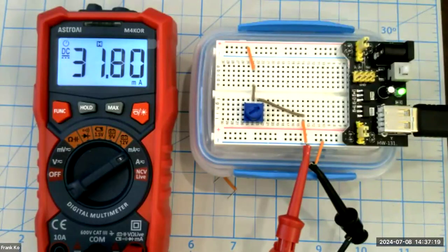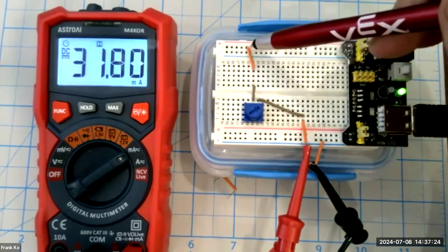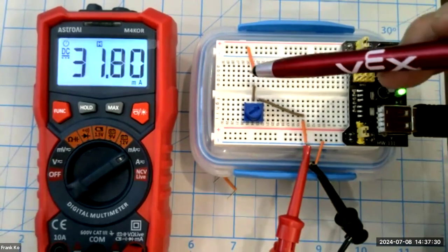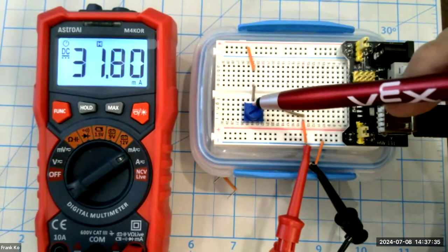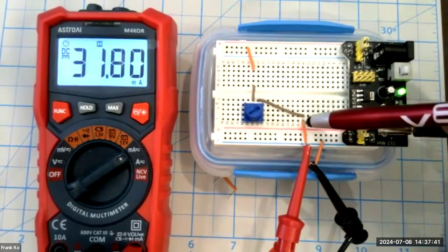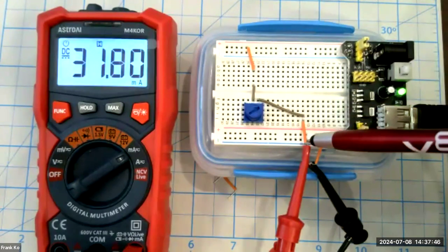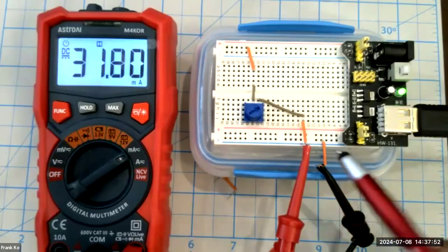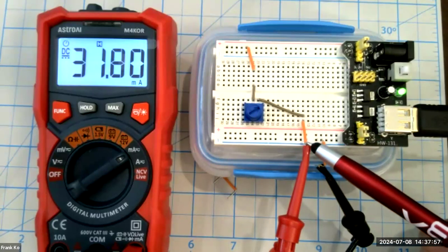Okay, so I've reconnected a couple of things. The orange jumper wire is now positioned up one so that it is now connected to the red rail. The red rail brings us down to this particular row 24. Row 24 connects with this brown jumper wire to the center pin of the pot, and one of the outside pins of the pot to here. I broke the circuit open. This orange jumper was previously connected to the blue rail. I've removed part of it so that it is now hanging up, and then the other part of the ammeter is hooked up down here. So I've created an open between this point, and I'm measuring between the open.